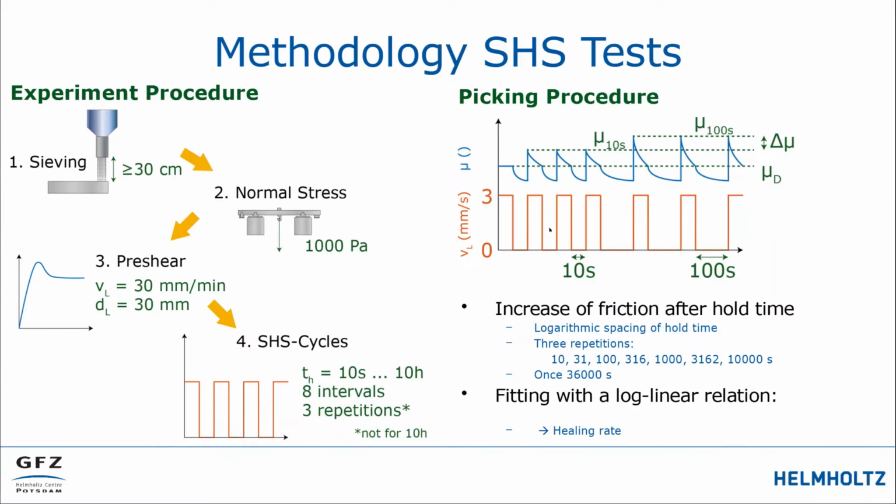And we plot this against the hold time. And we will see an increase of friction depending on hold time. And we fit this with a log linear relation, and from this fit we get a power law exponent, which is the healing rate.